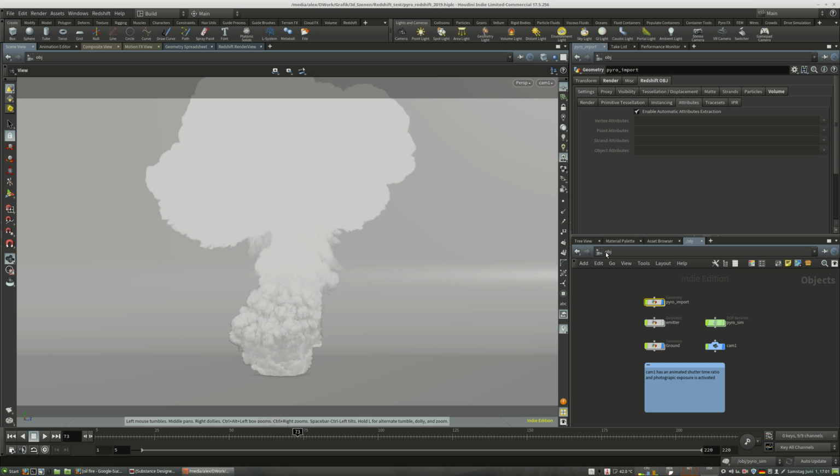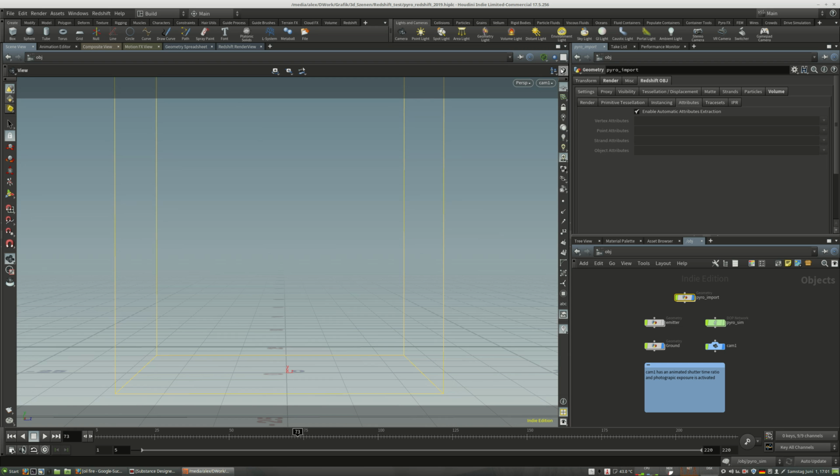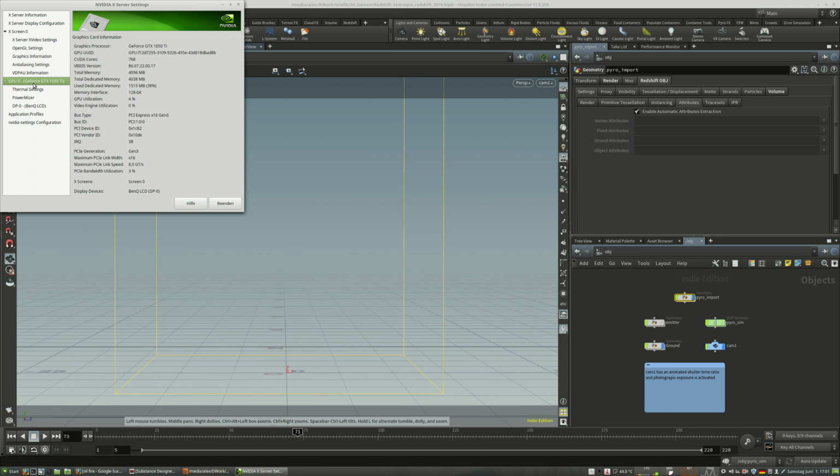And to shade those flames, especially when those simulations are very dense, you have to do some things to save some performance. So the first thing we do is we turn this to wireframe bounding box. So basically your GPU can save a lot of VRAM.